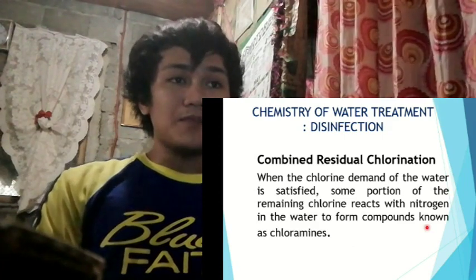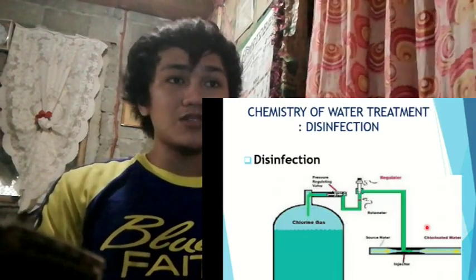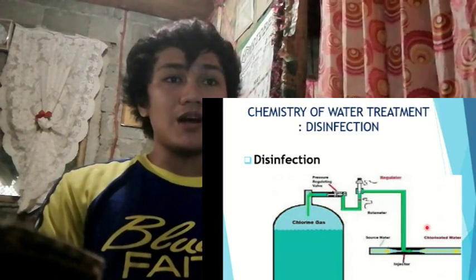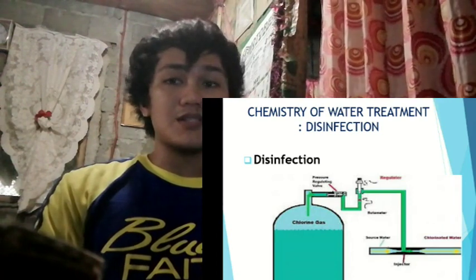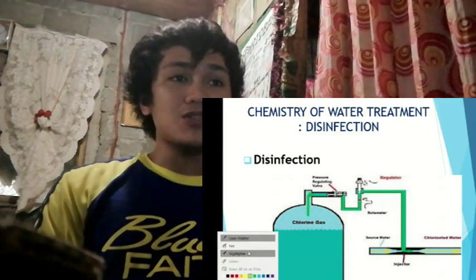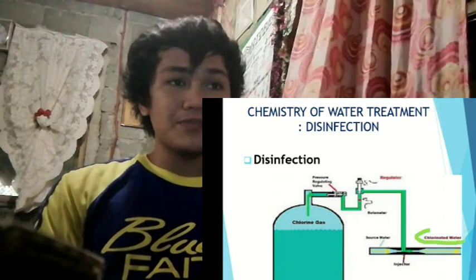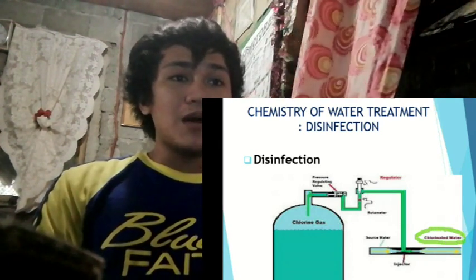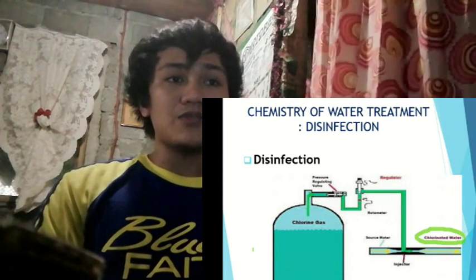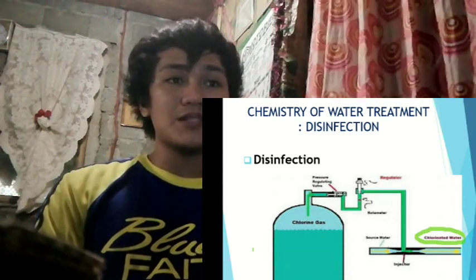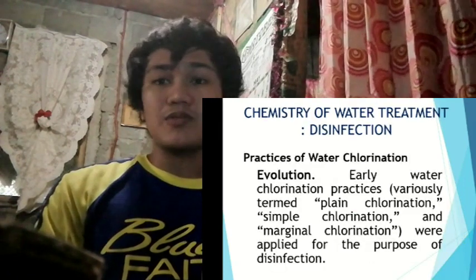Chlorine and ammonia reactions. The reactions of chlorine with ammonia are of great significance in the water chlorination process. When chlorine is added to water that contains natural or added ammonia, the ammonia reacts with HOCl to form various chloramines, which, like HOCl, retain the oxidizing power of chlorine.